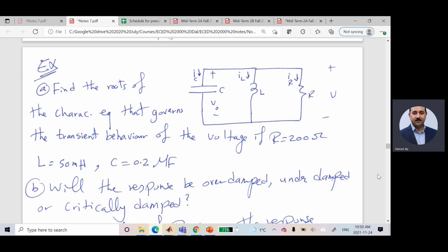And the next step is to write the equation that you are going to find for the voltage or the currents. And after that, there will be two different unknowns, two different constants, sorry. What are those? Maybe A1 and A2, or A1 prime and A2 prime, or beta 1 and beta 2, or beta 1 prime and beta 2 prime, or D1 and D2, or D1 prime and D2 prime. From where can I find all of these constants? I told you, from the initial conditions. So after writing the equations, I have to look at the initial conditions.